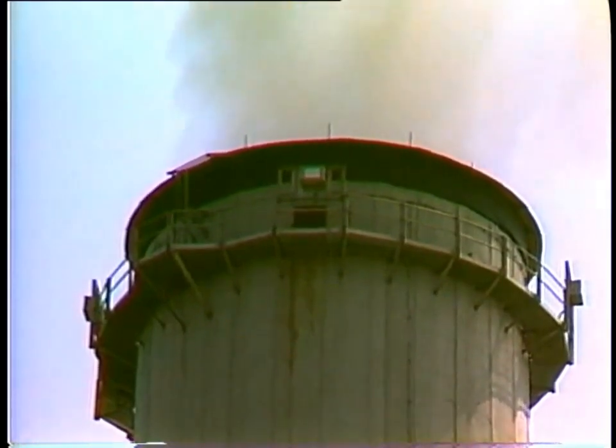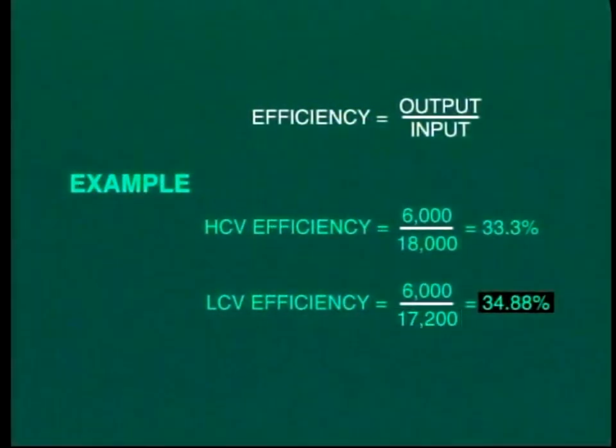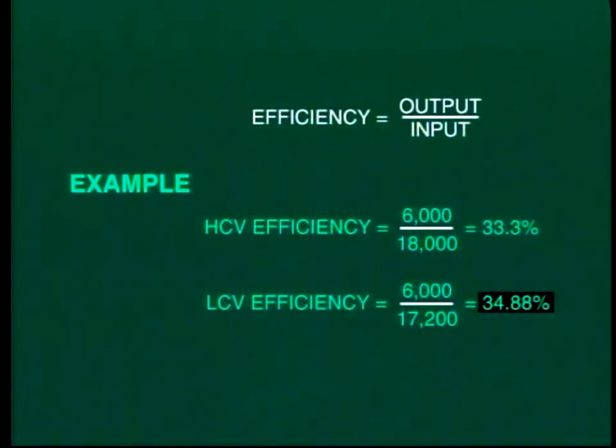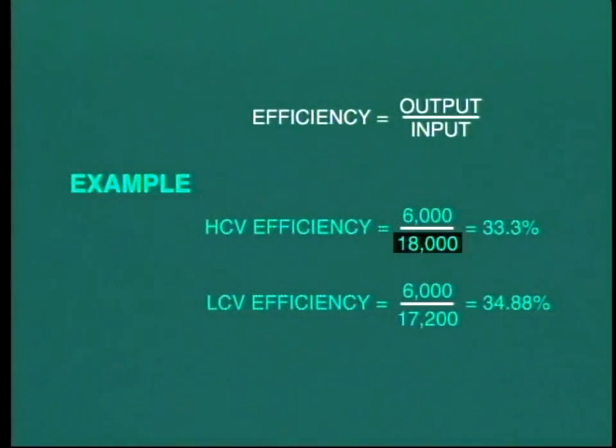However, beware. In many other situations, for example, in many European plants and European manufactured equipment, the quoted efficiency is based on the lower calorific value. This would, of course, provide an apparent higher number for efficiency. Clearly, if the heat input to the plant is indicated at a higher value, then the calculated efficiency would come to a lower number.